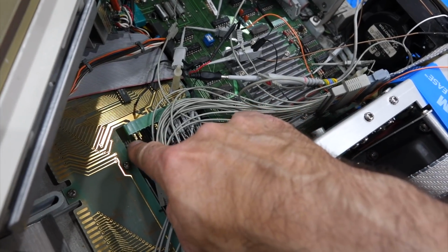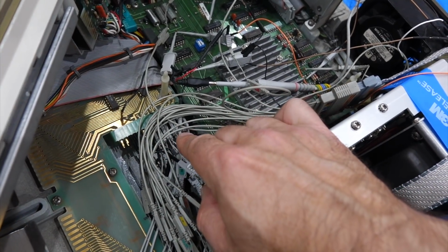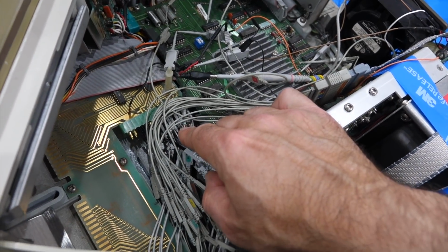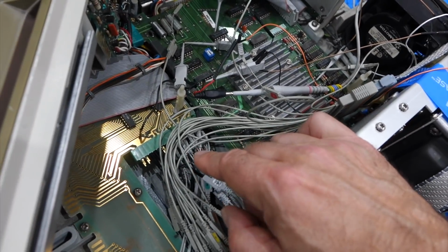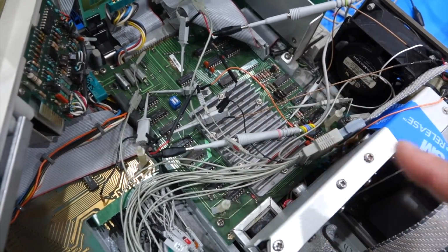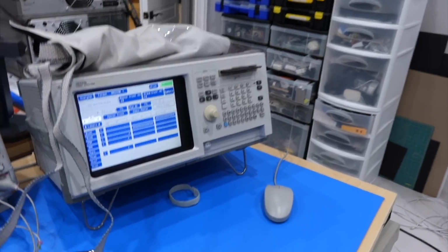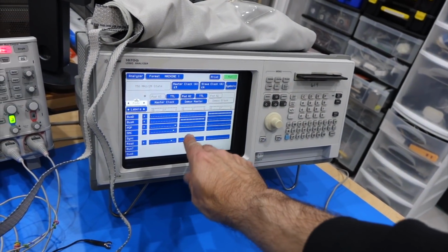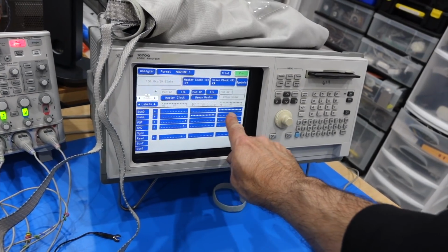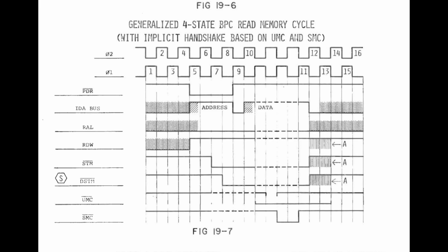And I had a connector that could go in it, so I have all my 16 address and data bits, because it's multiplexed and bidirectional. And then we have a few other control signals. And Carl, the master of the Logic Analyzer, has set it up to demux the bus. We have address and data. Multiplexed buses are a pain in the rear end, if you ask me.